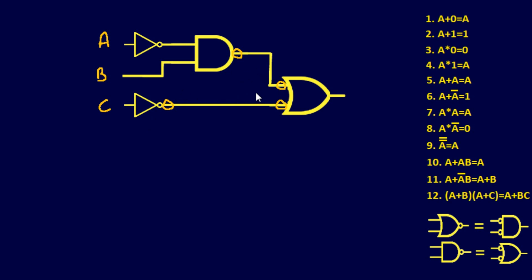Now, looking at this, that's a NAND gate, that's a NAND gate. However, we have one more gate that is not accounted for. We have an inverter. Unfortunately, I don't want to add any dots at the beginning here. However, I do want to get rid of this inverter. And as we talked about in the PowerPoint, a NAND gate that has its inputs shorted together will actually create a NOT, or an inverter, I should say. So A here would equal a NOT here.